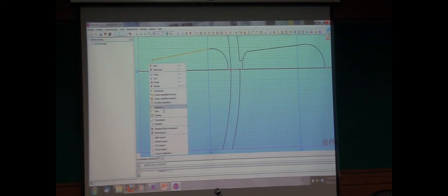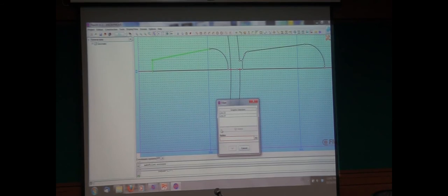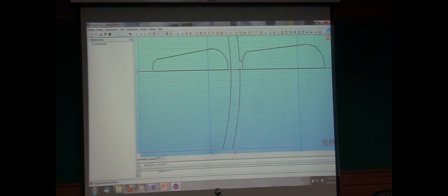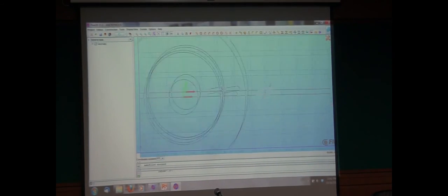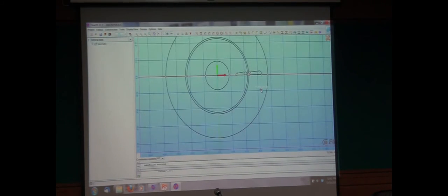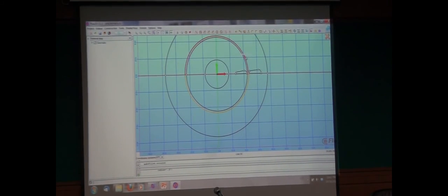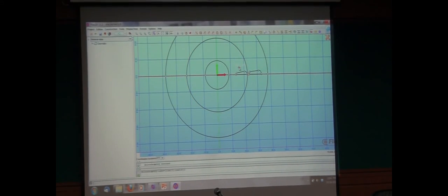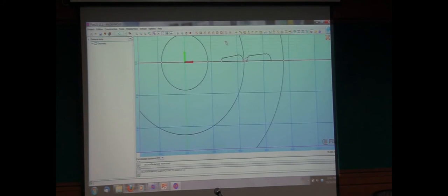Then I'm going to do the same at the bottom here and here. And again, the fillet. And let's just say 0.4 maybe. No, I can do a little more. 0.8. Okay? Now I have 2 pieces of my slots. I'm going to do the other side. And by the way, I don't need this part of the circle anymore because I've done my intersection, and I'll re-enter it after. But I need to remove it because I'm going to do duplication.